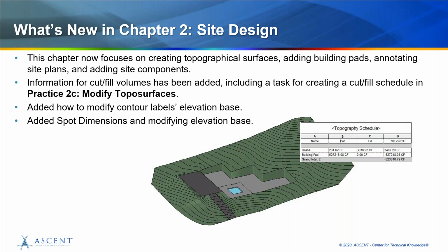One thing with any Revit calculations, you always want to tell your students that the cut and fill calculations are approximate, and that's to be said about all calculations within Revit. They generally provide a plus or minus of 1 to 2% accuracy.